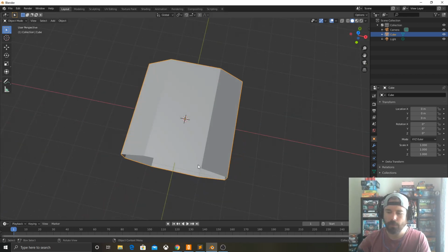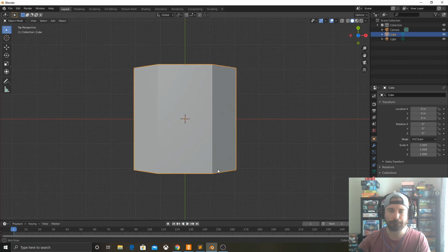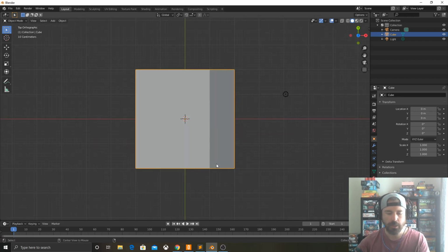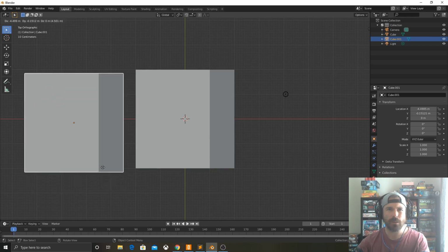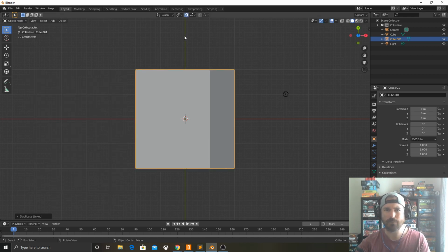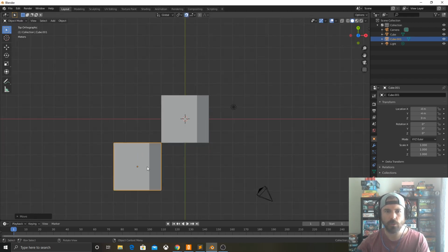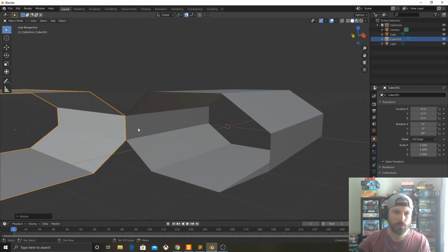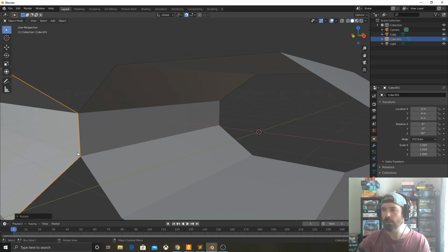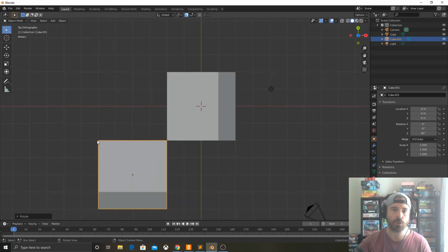But from here, what I've got top down here. Now I can easily duplicate this, Alt D, and I want to make sure that I actually have the snapping on here, so that go down there, rotate it by 90 degrees, and then you'll see right there, perfect join. Okay, this was something that I saw people in class struggling with, trying to get that perfect join there. But if you actually use the grid and build it modularly so that it does work on a grid system, then this won't be a problem.